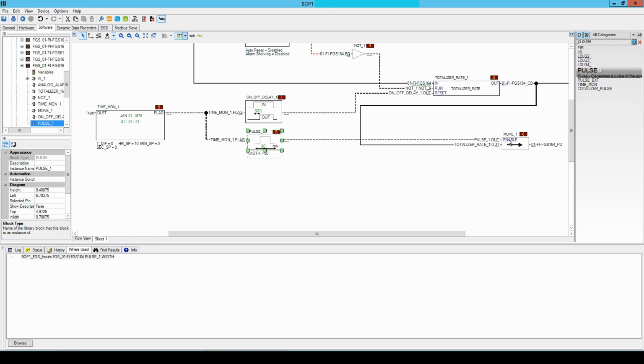What this enable pin does is when the enable pin is true, it writes the input to the output. But when the enable pin is false, nothing is writing to this output. So what I do is, first off, I take this pulse and I say, hey, when we hit the 10 a.m. on the day, wait 320 milliseconds and then reset it.